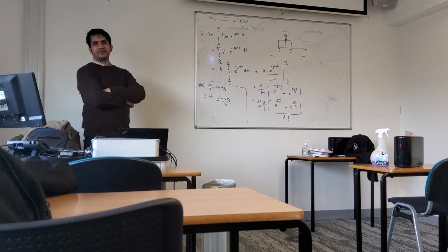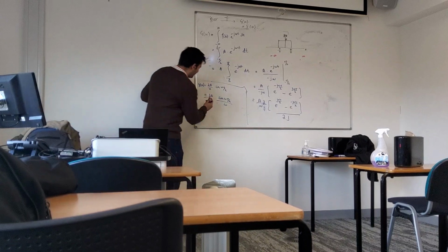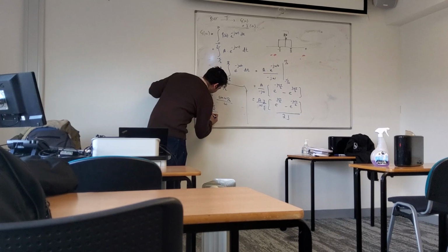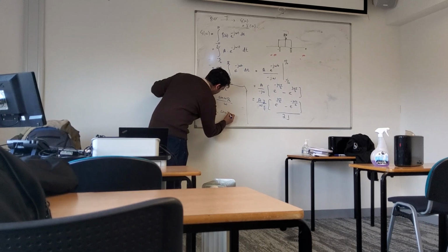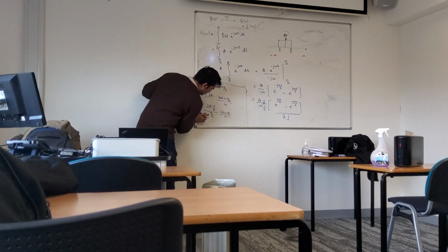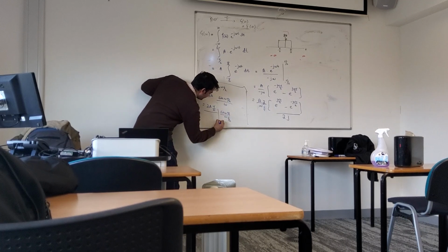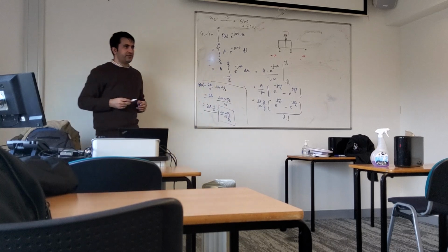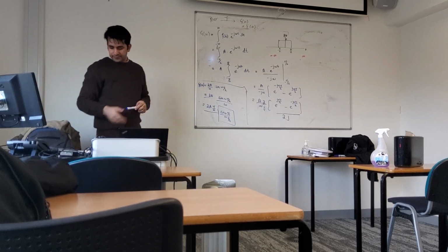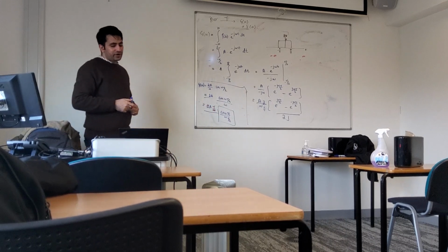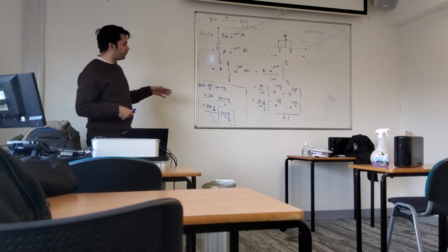So it means that I can simply multiply and divide by tau by 2, right? So what I can do is 2a sine of omega tau by 2, multiplied, and then the same thing I have divided, and by omega. So it means that this tau by 2 can come close to here. So now this looks like a sinc function, and this can cancel with this. So the final function is a tau sinc of omega tau by 2.